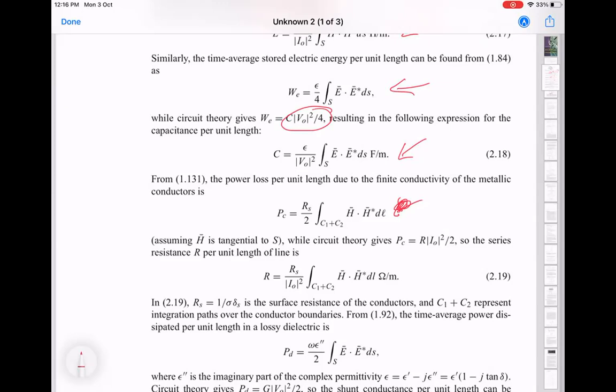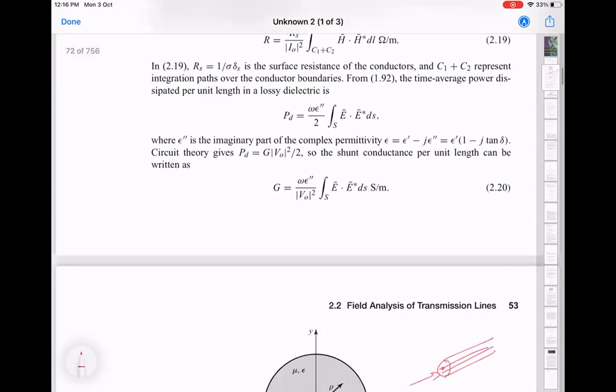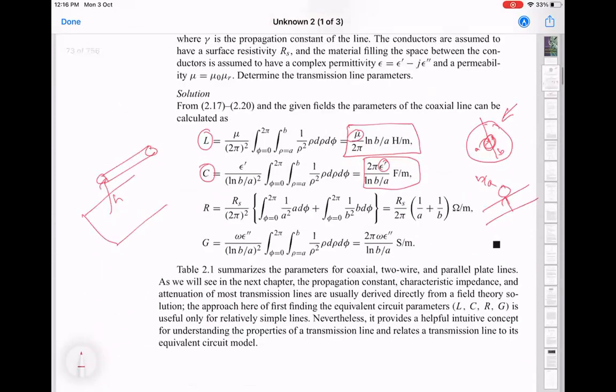But that's what I was saying, that practically speaking, you just buy these coaxial lines. You don't make them in-house unless you're making some small sections for very specific purposes. So it really depends on what you want for your characteristic impedance, because L over C is what matters. If you look at the ratio L over C, it will go as log B over A squared. And then there's a square root, so that will go away. So even Z naught is going to be proportional to log B over A. So depending on what Z naught you want, you choose B and A accordingly.